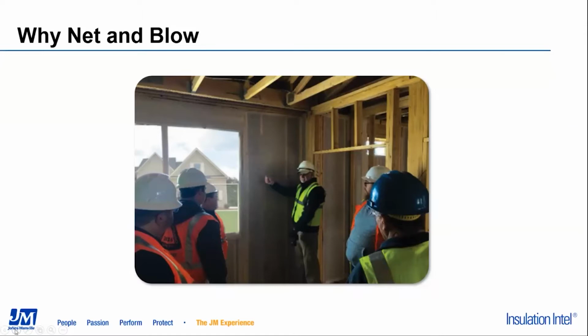Because of its uniform density and seamless coverage, the system creates a blanket of insulation that custom fits any size or shape cavity. This provides a uniform R-value throughout the entire cavity, and because of the higher density, helps reduce some of the air infiltration.